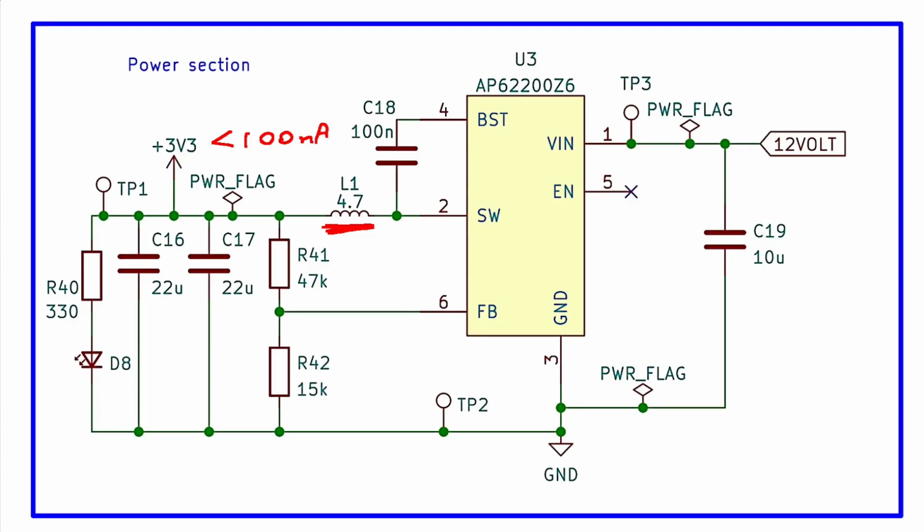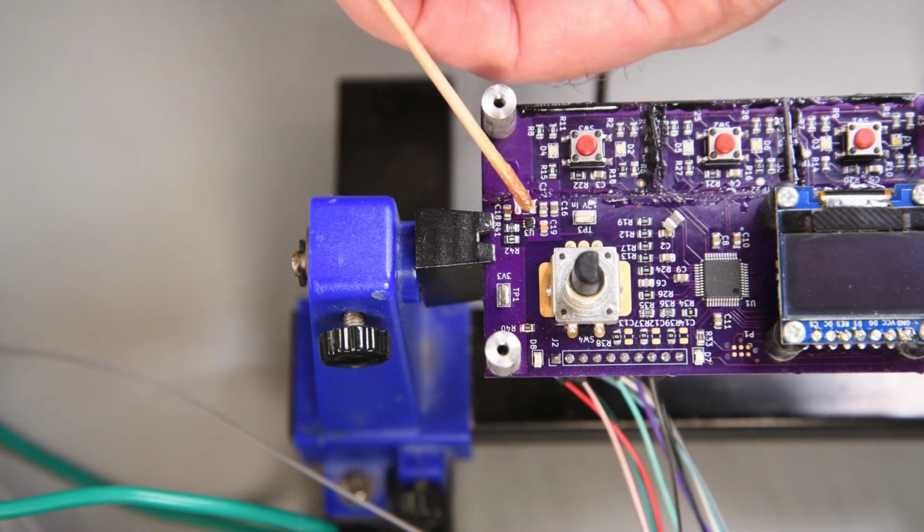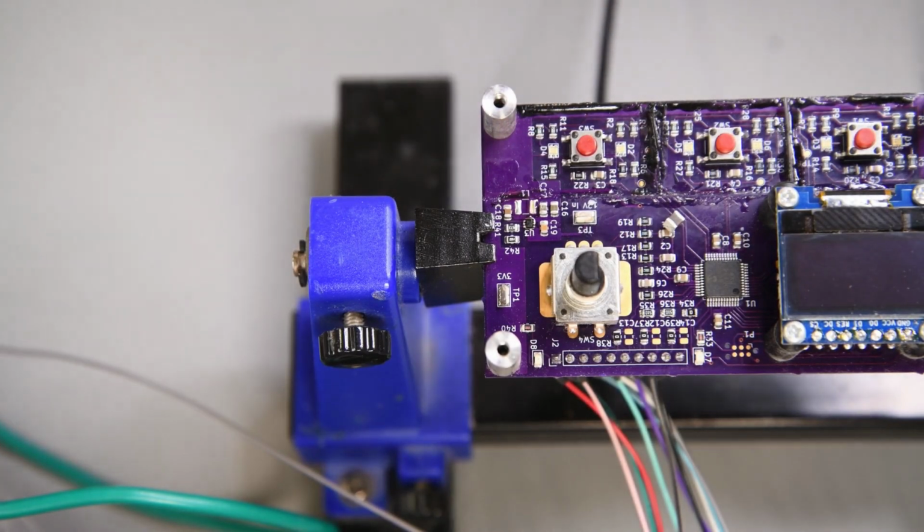I also ordered some 10 microfarad 50 volt caps to go in C19 here. What's in C19 right now is a 10 microfarad at 16 volts, which makes it maybe a 1 microfarad capacitor when it has 12 volts on it. I should have put a post-it note on the display board saying, "Update parts."